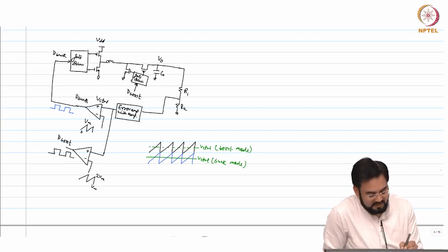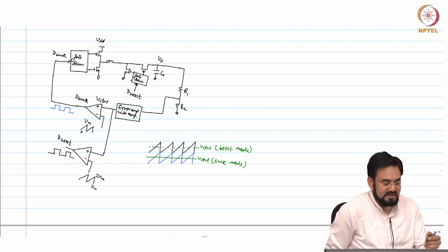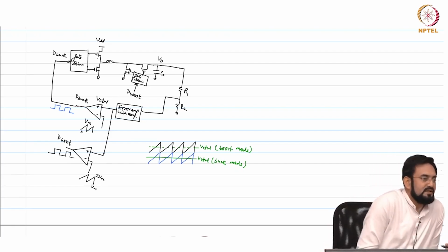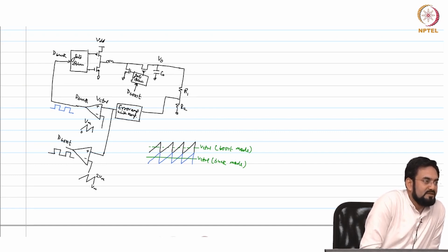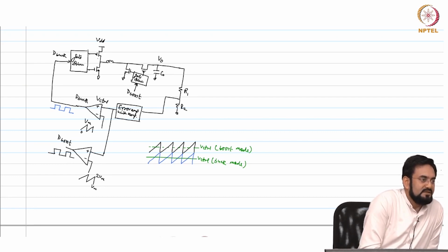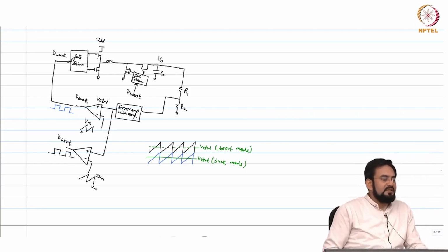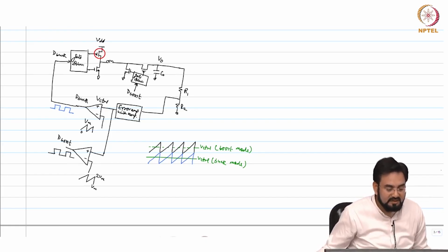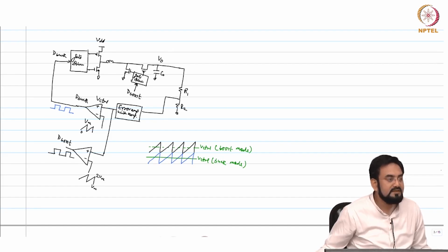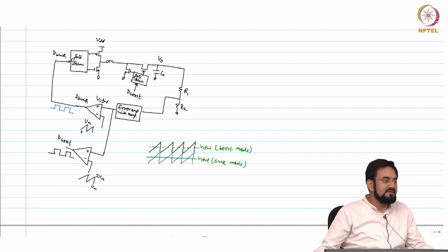Okay. So when your V control goes to Vm, that high side switch in case of buck will automatically be fully on. We already know what was the logic. When you operate in boost, you want this switch to be turned on, this guy, okay, and this turned off. So 100% duty cycle means this will be on, this will be off, and then these two switches will start operating.